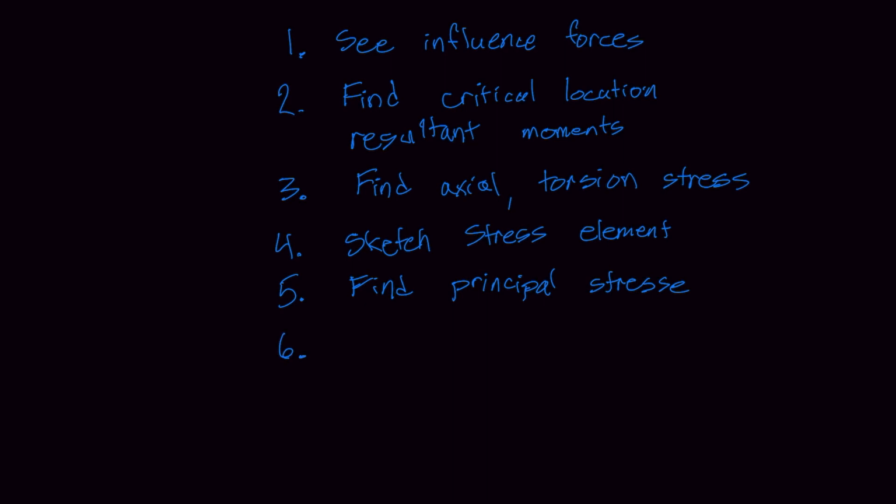And finally, I can check for failure with one of our failure theories like distortion energy or maximum shear stress. And this is the process I go through for most of my combined loading problems. Whenever I encounter a part or a problem where I need to take into account multiple forces and understand where a part might fail and what the stress values are at that location.